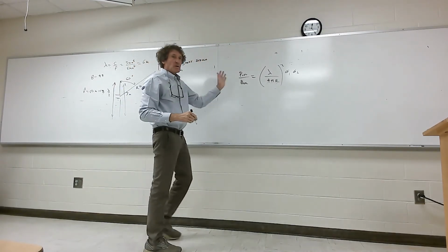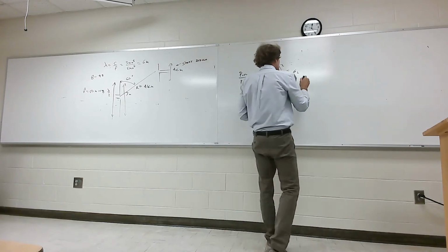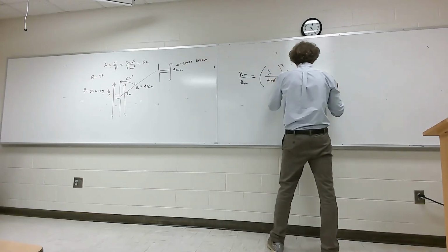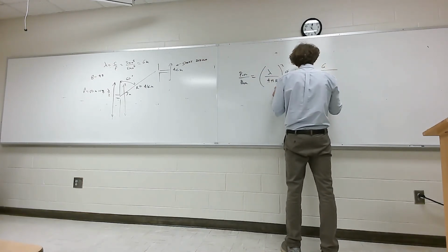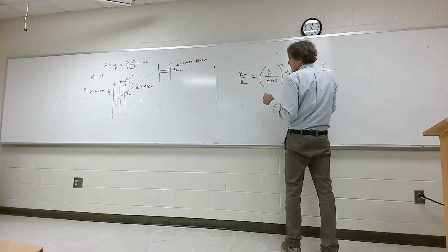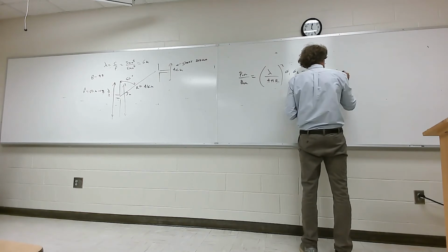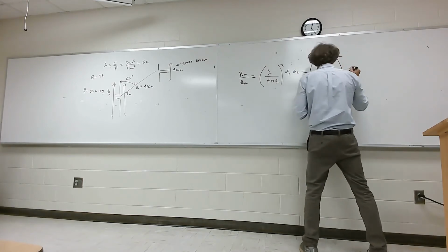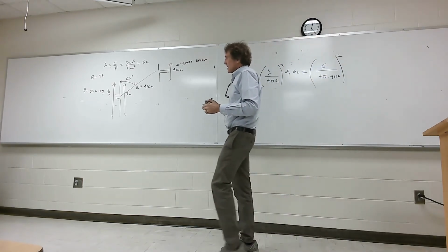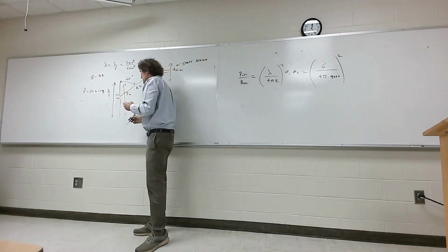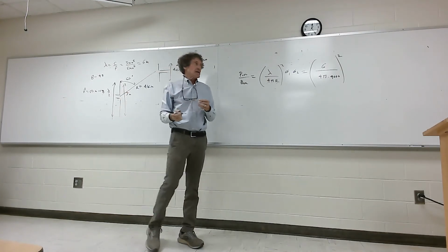Okay, now coming over to this equation, because we want the ratio, I got lambda, which is 6, over 4 pi. Then I got R, which is 4 kilometers, so it's times 4,000. I have to square that ratio. Then I need the gain of the first antenna. Now this is an ideal half-wave dipole, so the gain is going to be 1.64.